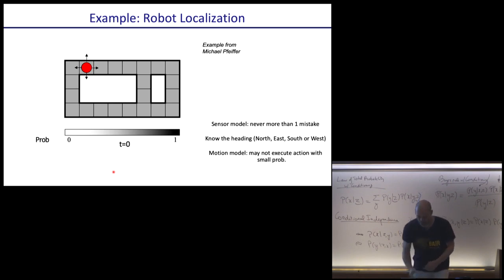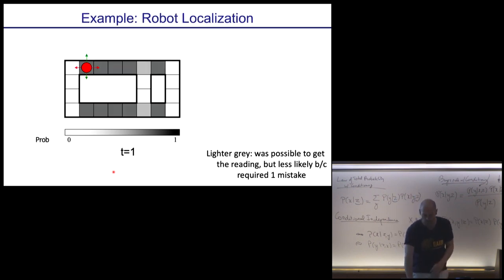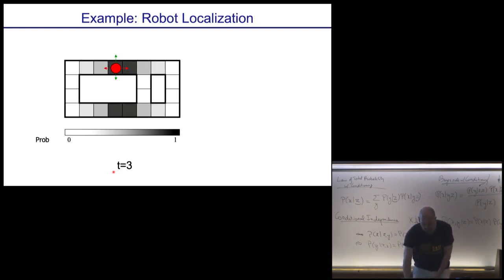It gets a measurement and says, wow, I only see things above and below me, not to the sides. So the Bayes rule update will result in the new distribution. Then it might say, I'm going to move. But it might have noisy motion, so it spreads out the distribution a little bit. Then it measures again, which shrinks it again. And this process repeats over time, and over time it might localize itself in this building. Of course, this assumes access to a map of the building. Otherwise, this whole Bayes update rule wouldn't work out in this case.